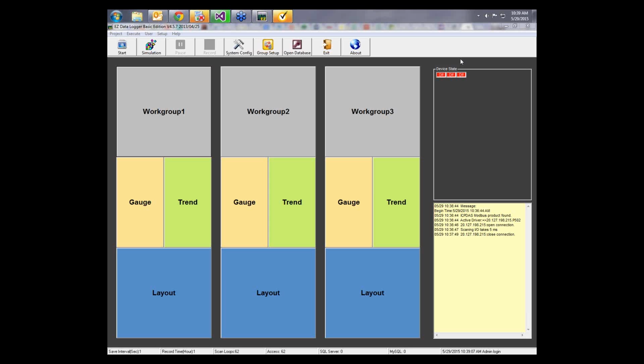Shakar asked, what is the piggyback configuration? The piggyback configuration is when you take the little clip that comes with each module, unscrew the screws that hold the case together, mount the clip that came with the module, then put the screws back on and mount one module on top of another onto that clip.